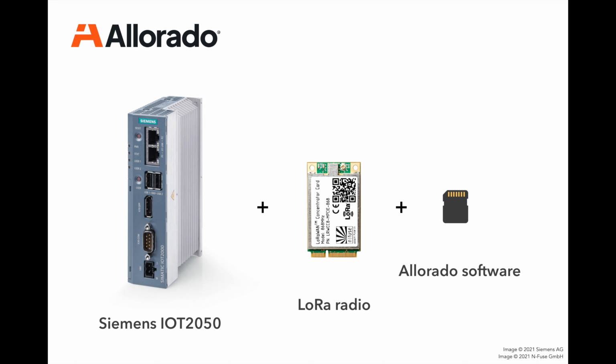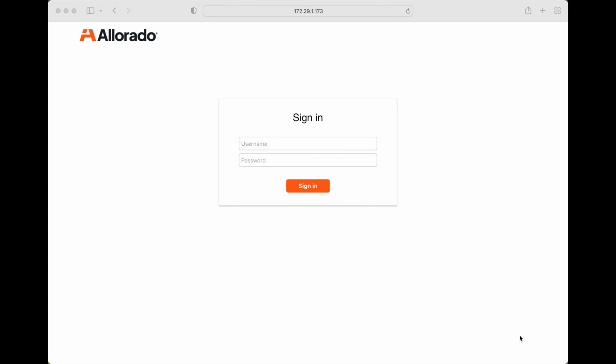With the decoded payload available in NodeRED, you will be able to use that information in your flows to do whatever you like. For example, convert it to other protocols like Modbus, OPC UA or KNX, or even send it to the outside world to a platform of your choice. The possibilities are endless. Let's get started with the setup of a LoRa device via the web interface.